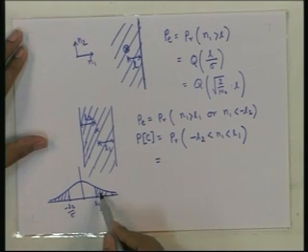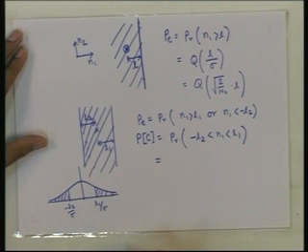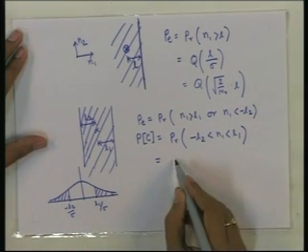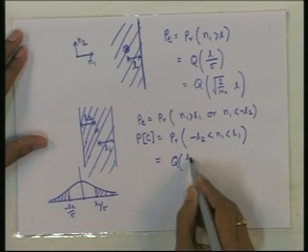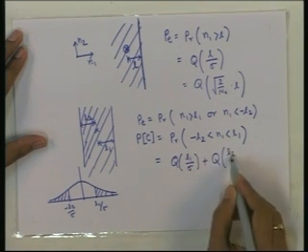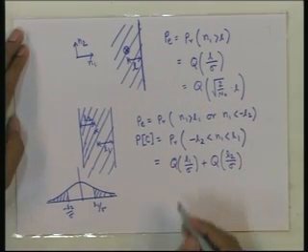Note that this area is Q of L1 by sigma and this area is Q of L2 by sigma. This is minus, but this area is same as on this side. If you take this point on this side and take Q function, it is the same, because the Gaussian PDF is symmetric. So, these two areas together are Q of L1 by sigma plus Q of L2 by sigma. This is the probability of error.